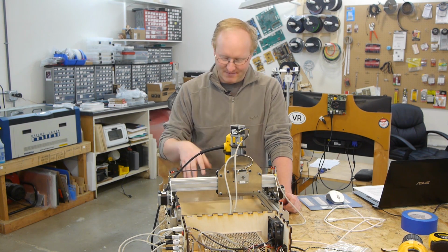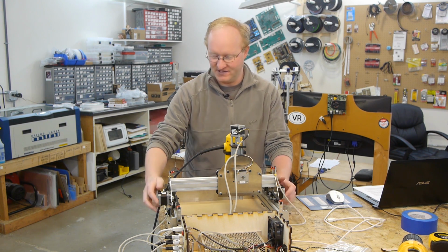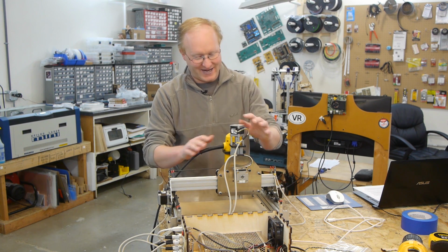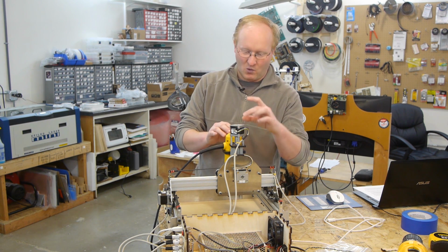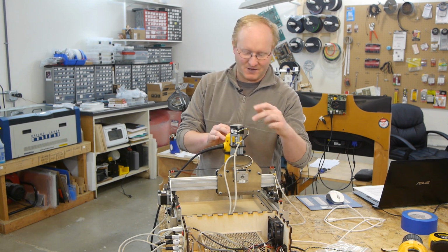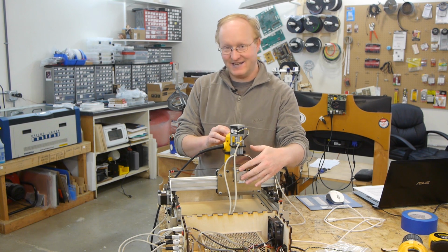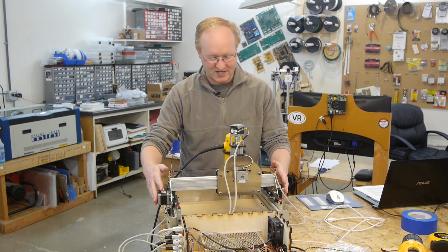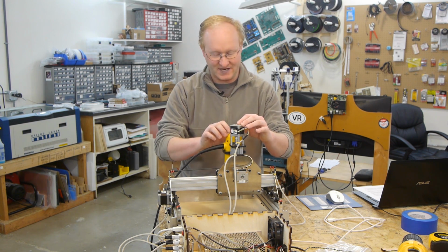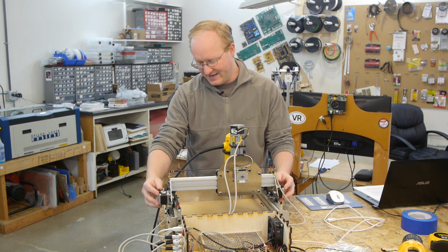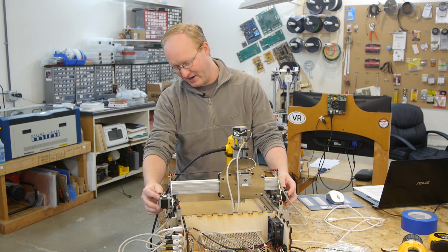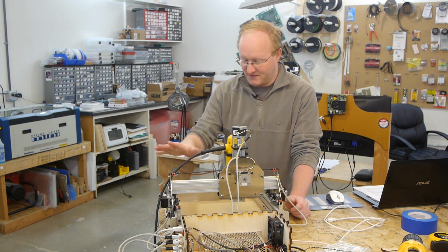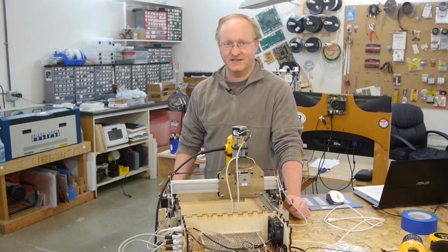One reason a machine might move the material back and forth instead of this large gantry is because everything you have on the gantry adds weight. So what this motor has to move isn't as much as what this motor has to move, and it's not as much as what these motors have to move. Of course, there's two of these. These motors have to move all of this weight, whereas this motor just has to move this weight. So it's kind of about distributing the weight. But I like these systems just because it's more straightforward and you don't have to worry about the piece moving in and out and clunking against stuff.